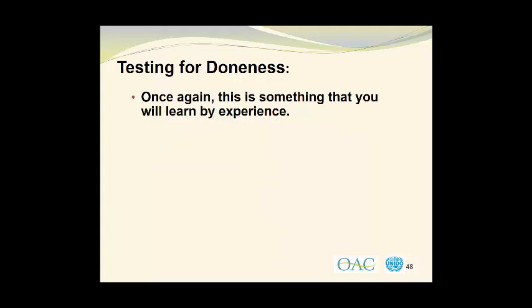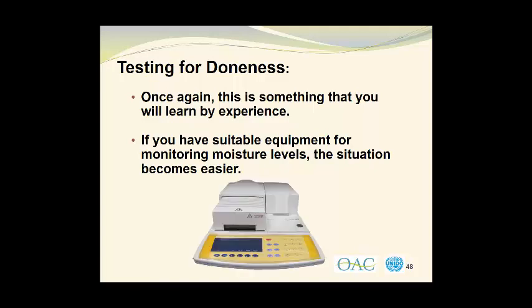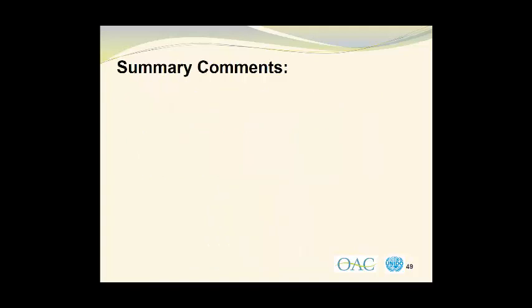Once again, this is something that you will learn by experience. If you have suitable equipment for monitoring moisture levels, the situation does become easier. And here we have a laboratory moisture balance, which gives the moisture content to 2 decimal places, and that's a little bit more accurate than most people have for their endpoint determinations.